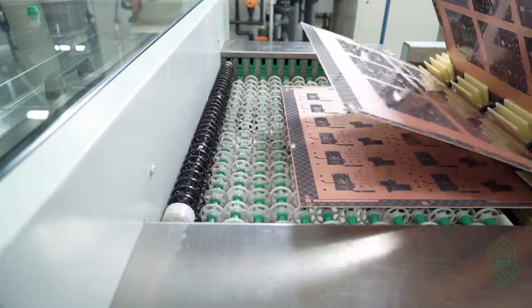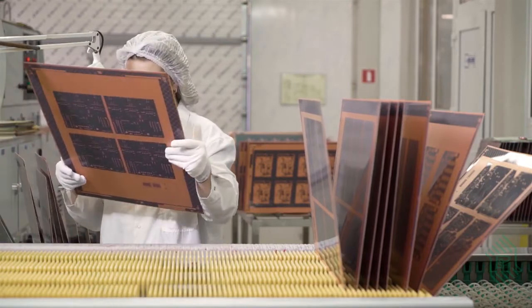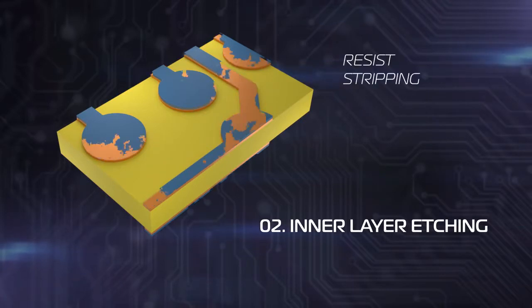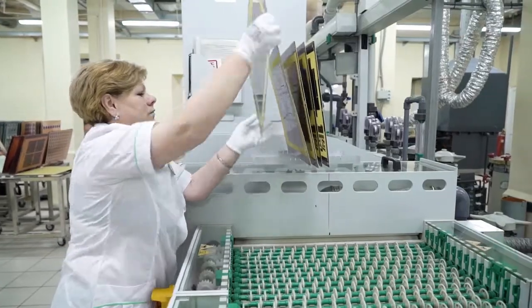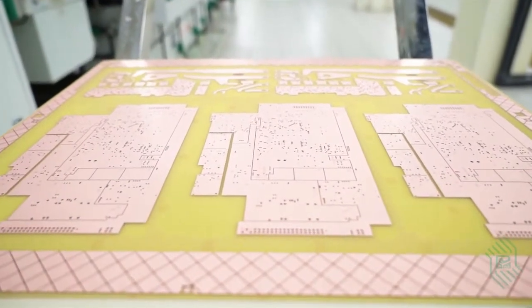The final stage of the development process is quality inspection, after which the panels are transferred to the etching of the inner layers. Etching is carried out in a horizontal conveyor machine. The copper unprotected by the photoresist is etched away, thus defining the pattern of the multi-layer PCB inner layer. Following the etching, the photoresist is completely removed in a special line for its removal.